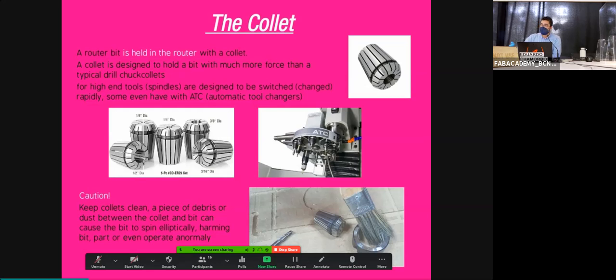When you are in a professional environment, you want to automate your job a lot. That means you need a lot of end mills for different purposes. We have what is called an ATC, an automatic tool change. It looks like a machine gun with a lot of end mills already mounted with the proper collets, and the machine comes, takes one, goes, cuts, comes back, releases, and takes another one. This is a super nice accessory, but it's an add-on that is quite expensive in general.